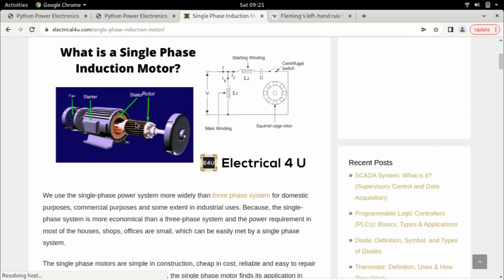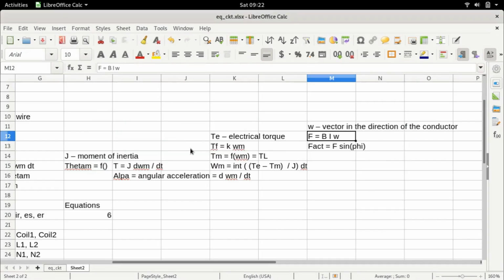It is the length of this rotor bar. Since now there is one little peculiarity which you can look at here: these rotor bars are skewed, right? They are not exactly parallel, or rather they are parallel to each other, but they are not exactly along horizontal. They are skewed, and there is a reason for that. Usually it is skewed to reduce vibrations, but again, that is a complex concept. Assume now that these rotor bars are not skewed, rather they are horizontal. In that case, the length of this rotor bar is this W which we are talking about, right?